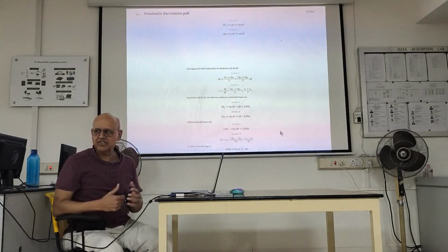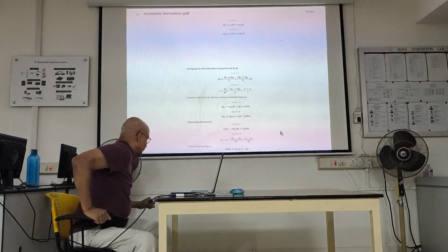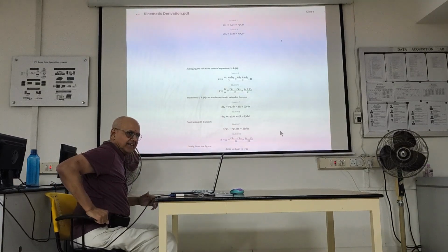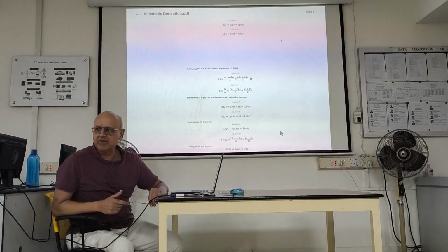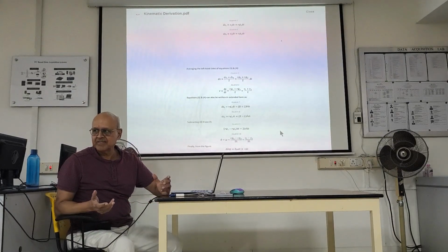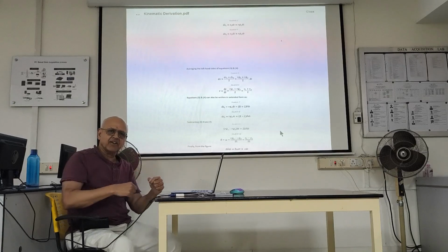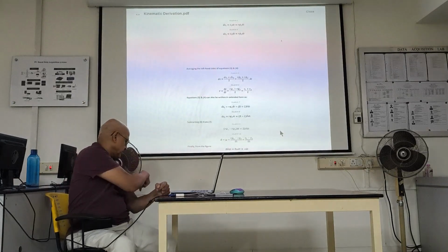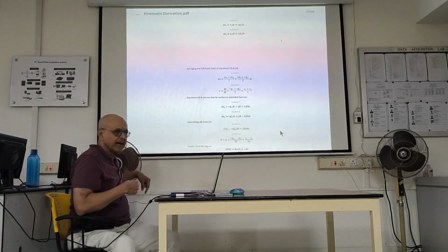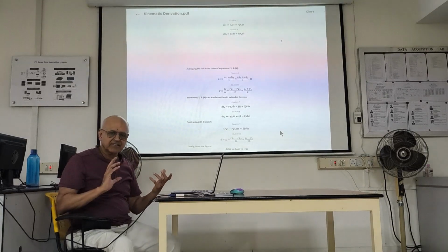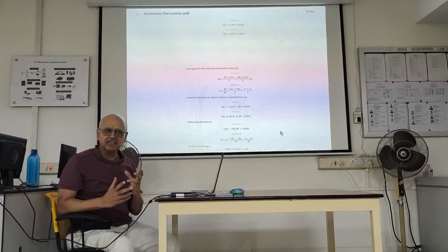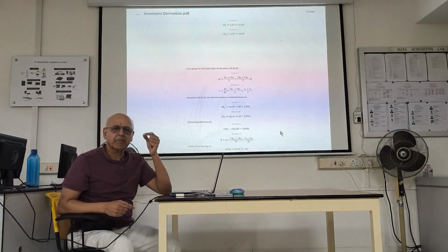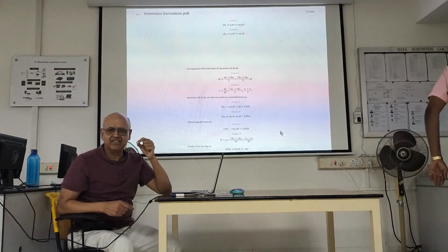But what about a differentially steered vehicle? I can just rotate in place like this, right? And I can get here. So it's much more maneuverable than a regular car, right? Because even the car, if you turn the steering wheel all the way to the stop, it might not be able to get here. It might have to drive out and come back. Whereas a differentially steered vehicle can pivot in place. So that is the beauty, because it has the possibility of 0 radius turns.